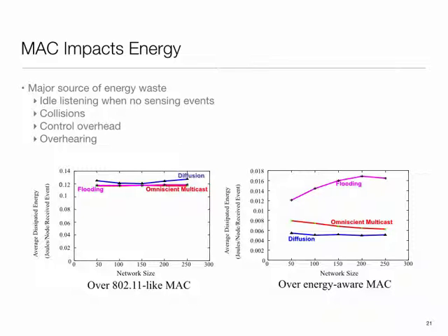Your flooding, which is so blatantly inefficient, does as well as the smarter routing techniques, because the receivers are up and listening all the time, and therefore negating all the advantages. Whereas in a MAC protocol where the receivers can be put to sleep, you begin to see these differences. So it matters how you manage the sleep state of the radio.